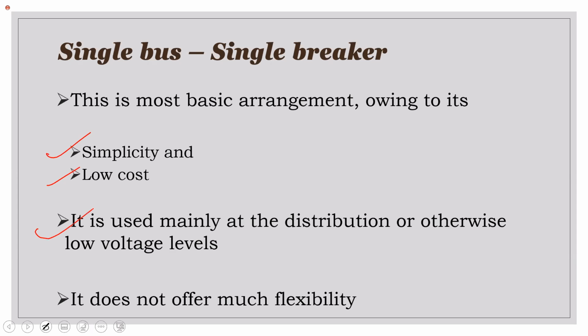Right? Used at low voltage, but it doesn't offer much flexibility. The bottom line is, if you have a fault, it trips. You may have a reclose on it, but if you don't, it trips. Somebody has to go check, clear, and reinstall, and return to service.